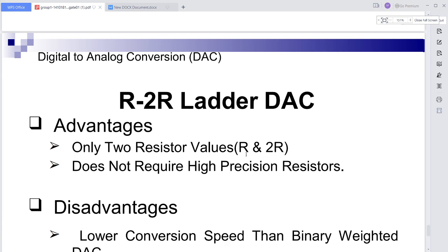So the main difference here is that we interchange the LSB and the MSB, such that every bit is connected with its equivalent positional weight, and we can avoid the current fluctuations, because we are putting the values of resistances with respect to the positional weight. Anyway, the op amp is also at virtual ground, since both the terminals of the switches are at ground potential, the current flowing through the resistances is constant and independent of switch position.